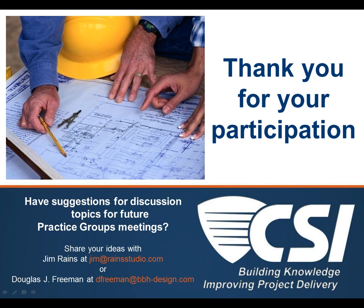That's a great subject. Let me say one last thing before we go on reviewing shop drawings and submittals. As we said before, we're not responsible for dimensions and quantities. My advice to you is, when you get a shop drawing in and you see a dimension that is not consistent with the dimensions in your drawings, do not cross that dimension off and change it to what you had on your documents.